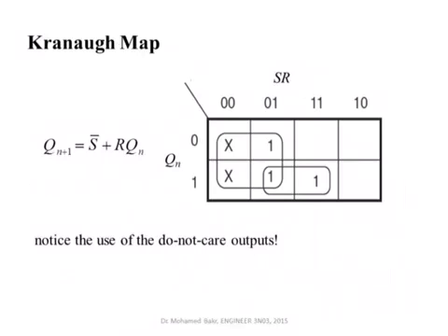Okay, we can build a Karnaugh map as we explained before in the lectures on how to. This will help us simplify the implementation of this RS flip-flop. So I brought here all the possible combinations for the inputs RS: 0, 0, 0, 1, 1, 1, and 1, 0. As we agreed, when you have 0 and 1, the flip-flop will be set, so you get here 1 and 1. Okay, and here you should understand this Karnaugh map shows Qn plus 1, the new state, using the input and the current state.